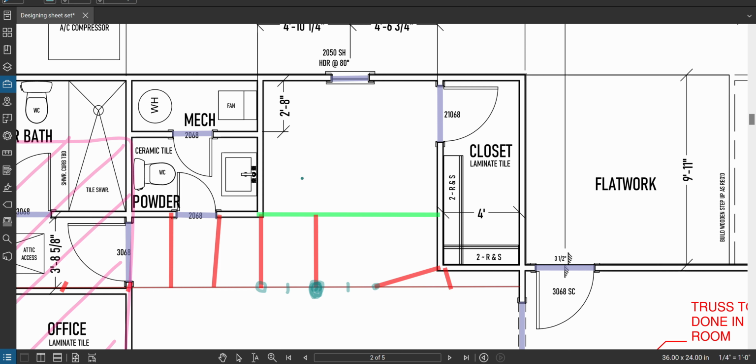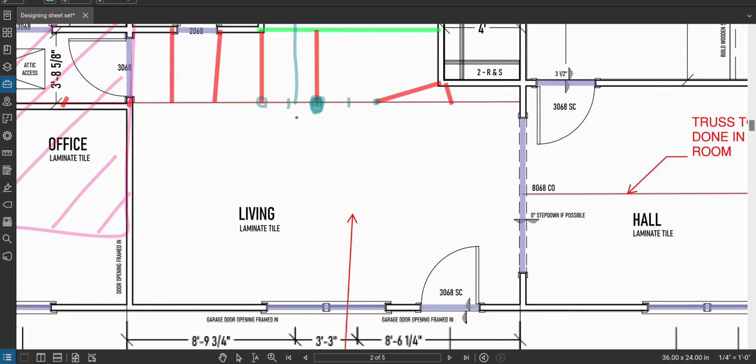Well, half the weight of the rafter is going to go to the wall, half the weight of the rafter is going to go to the ridge. So somewhere about halfway, here's the rafter. It starts on the wall, comes up to the ridge. Boom. Somewhere along that halfway point is where I'm responsible. Okay. Same thing on this side. I'm going to draw my rafter right here next to my line.